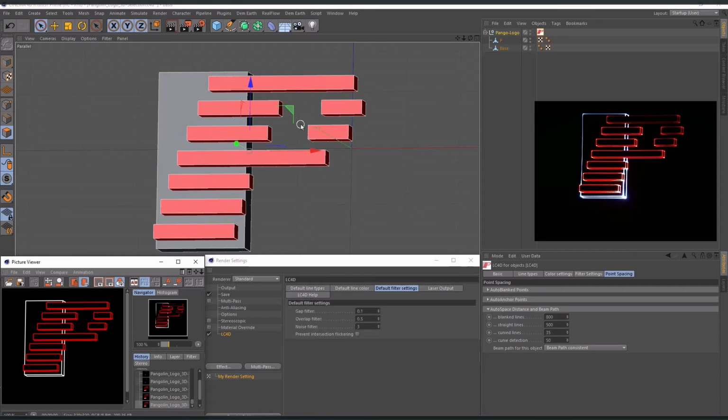I recommend to simply play around with those parameters and watch the real laser output. So, for example, if I set the value too high, like 800 or something, you can see that those normally sharp edges of those red boxes are now starting to become really roundish, and so you have to evaluate the limit of point reduction in your project to avoid insufficient image quality of your rendered laser frame.